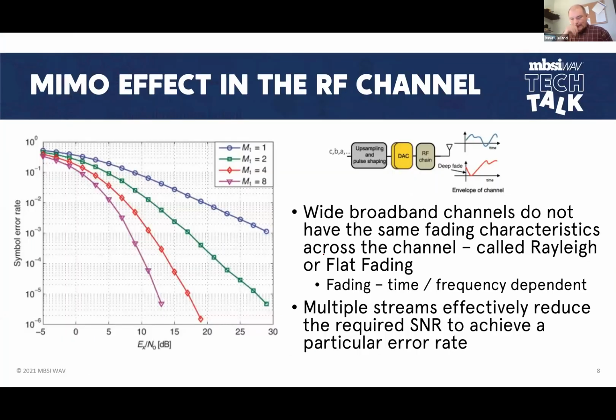All right. So the effect in the channel, what does it really mean? All right, let's start here with my little channel response here. What we have is just simplified it here. We have one chain, and in fact, we know there's two. As the two sets of symbols are being transmitted, even though they're in the same frequency, and even though they are within the same channel, the envelope of the channel, or the channel response, is very different for the two. So this is the whole point of the joint equalizer. We need to do that. This is what the channel in fact looks like.